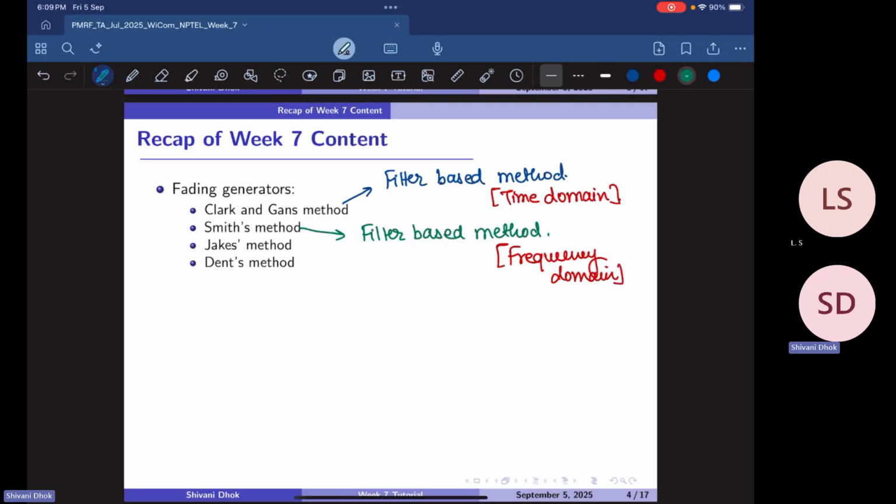So basically what we do, we take the Fourier transform of your AWGN, your uncorrelated noise, and then we also take the Fourier transform of your filter, the same filters that we had here, and we multiply them in frequency domain and then invert them. Now the good thing that we can do here is we can generate Gaussian random variables in the frequency domain as well, instead of generating them in the time domain. We just need to take care of the symmetry of the Fourier transform while doing that.